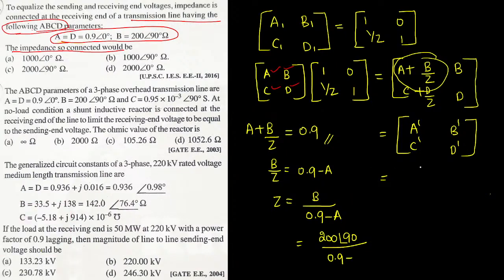Let me go through. Listen guys, I already told you, when no network is given, and in this case only the ABCD parameter is given without saying clearly which transmission line, then by default you can take that it is a short transmission line. I thought that they didn't go with this assumption, but they went with this assumption only. Then only you can crack this question.